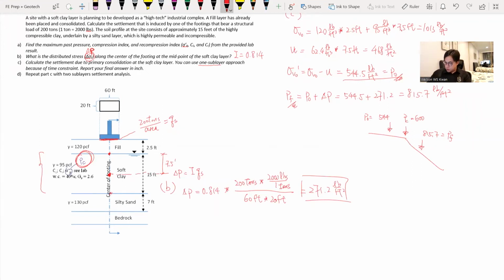And we also know the slope of the recompression part and the slope of the compression part. Settlement analysis pretty much is solving a point-slope problem of the consolidation curve with the known information. And pretty much we want to find the delta e, right? Remember that? So this is the delta e.